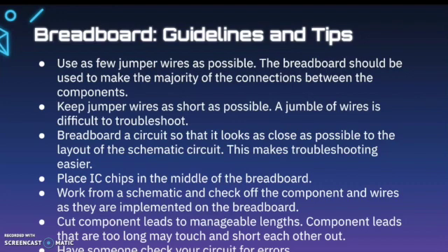Also, you should always work from a schematic and check off the components and wires as they're implemented on the breadboard. Taking screenshots of our circuits and then using an application like Google Draw to highlight when you've inserted something is a good practice.